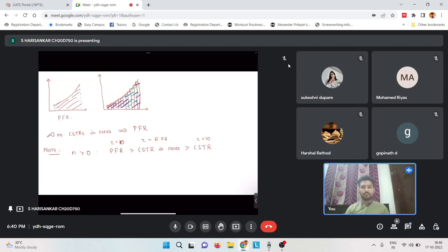Okay, so when your order is greater than 0, so if it is a positive order reaction, something like A gives B or A gives 2B and so on, PFR will be the best choice for that, followed by CSTRs in series. So if you are not able to do it in a PFR, CSTRs in series is the next best option, and then only the CSTR is the least preferred option.